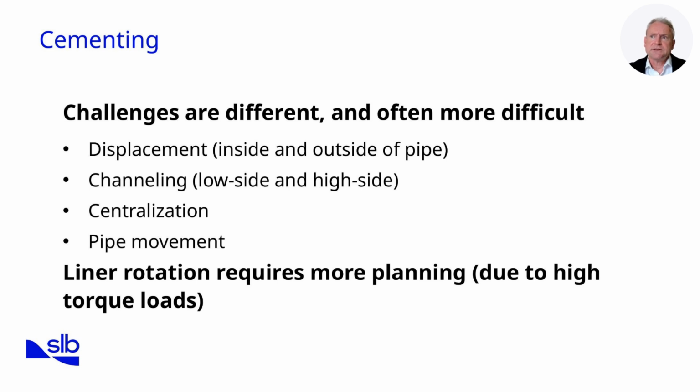Pipe movement, both reciprocation and rotation, is one of the best tools we have to improve displacement, but in ERD, this requires careful planning because torque loads are high. Liner rotation in particular can be limited by friction and buckling, so torque and drag analysis must be done ahead of time. The key takeaway is that cementing design for ERD requires a higher level of planning and execution discipline than in conventional wells. Once the well is cemented, the next critical stage is completions, where drag and buckling issues often reach their peak.